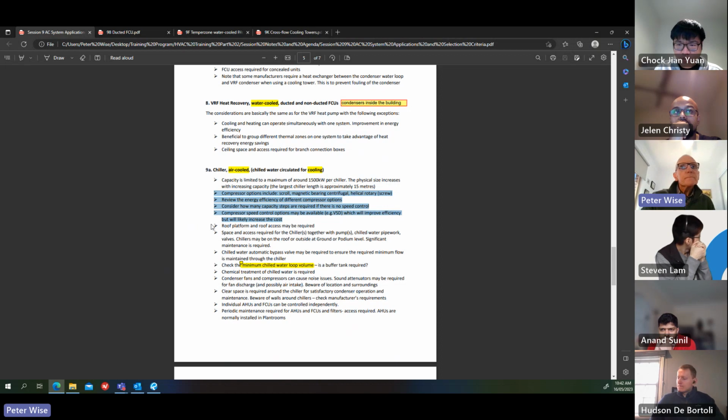But some compressors, like a scroll or a centrifugal compressor, are available with a VSD. A magnetic bearing centrifugal chiller compressor may come with a VSD integral with the compressor, but just check that it has got that. But for a screw compressor, you'd need to pay extra money for a VSD, and that's available to increase the energy efficiency.